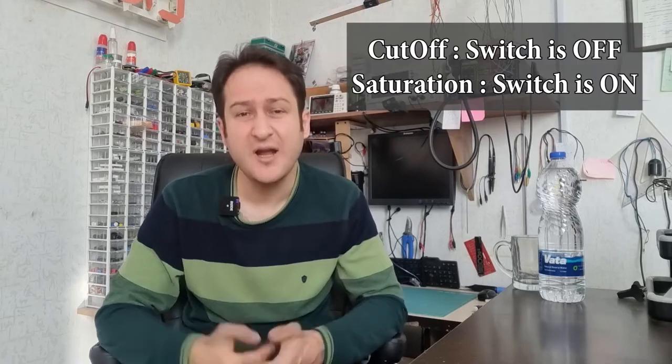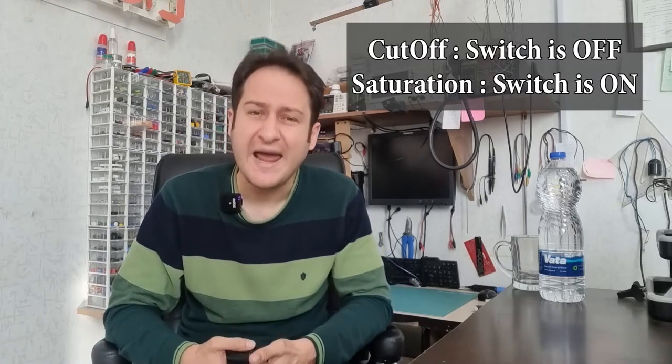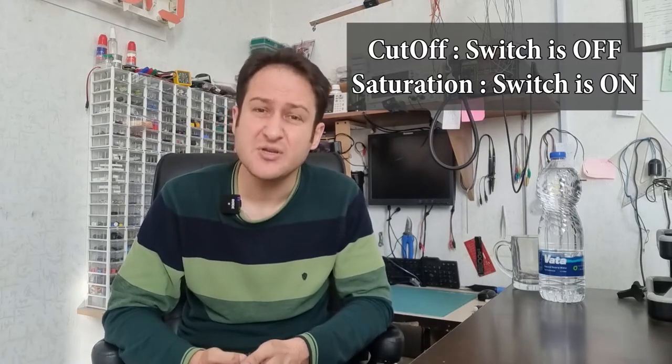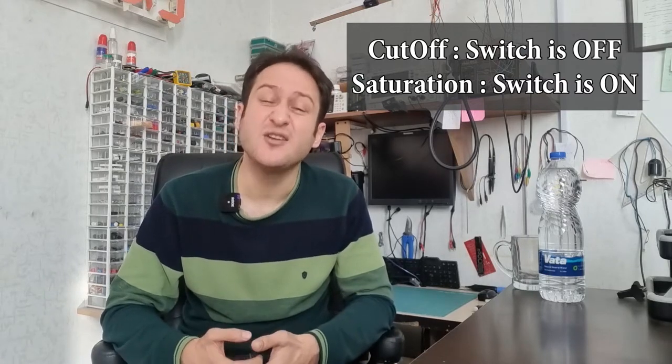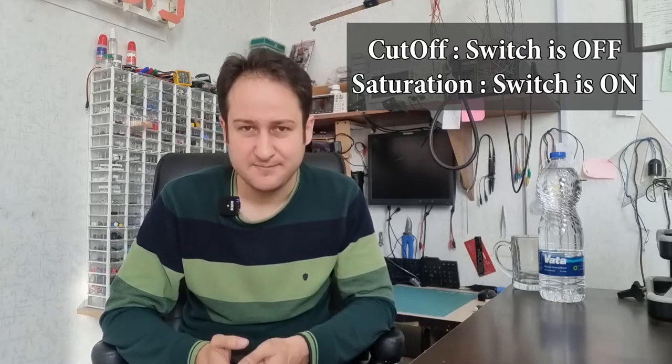When the transistor is to be used as a switch in digital circuits, it must be in only two modes of operation. Cutoff mode, in which the transistor acts like an open circuit when the switch is off, and saturation mode, in which the transistor acts like a short circuit when the switch is on. Transition between these two modes of operation is easy and straightforward in NPN type transistors. Because of that, NPN type transistors are handier and more useful and more seen in today's circuits.